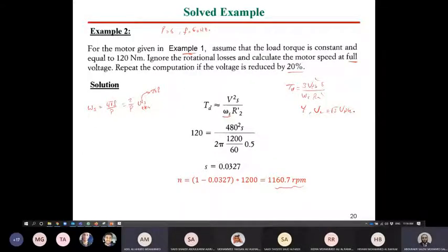So we said that omega S is the flux speed, right? Omega S is the flux speed. Yes, this is right. However, flux speed means rotation of the flux in the air gap. So is it electrical or mechanical now? So it should be electrical, right? No, it's not electrical. Moving of flux in the air gap, it's motion. It's mechanical motion now. It's not electrical motion. Because now it's a function of number of poles of the machine. However, electrical motion is a function of frequency only.